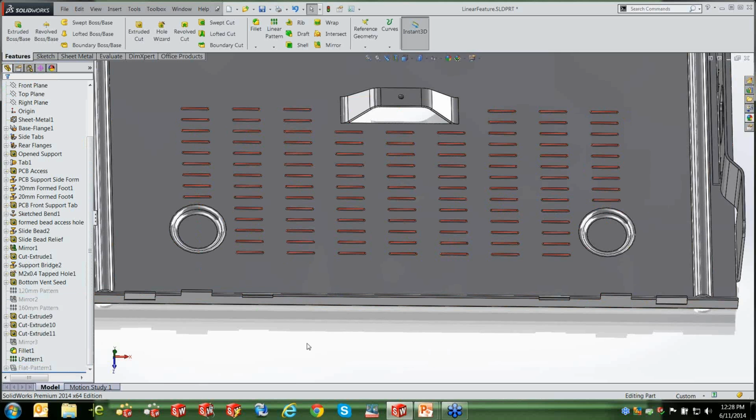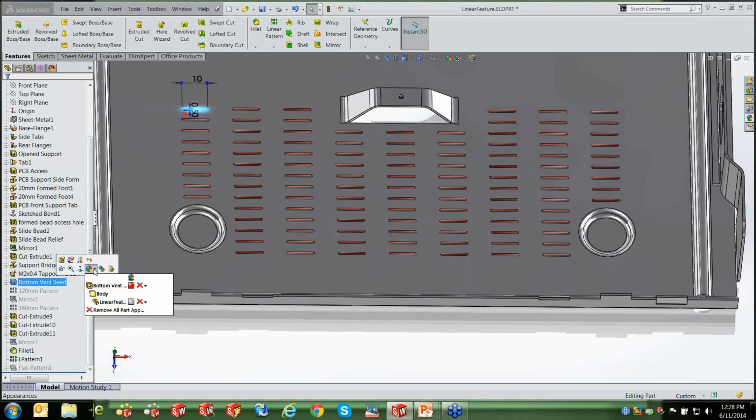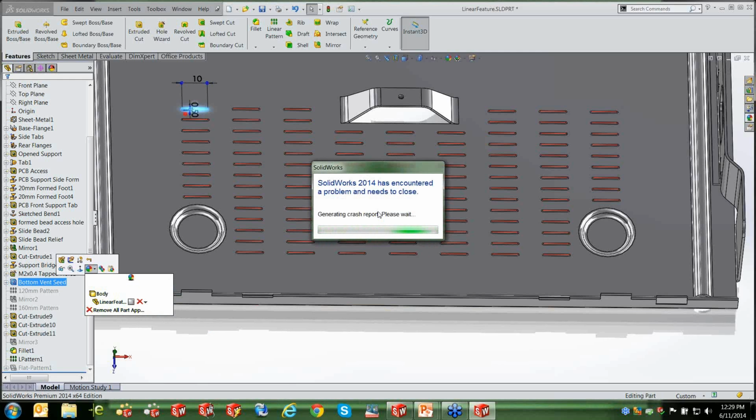Very simple. The gotcha on that one is when you go to change the color, you've got to make sure you change it and apply it to the feature, because it's moving the feature colors along with it. It will see if there's an individual face, but if you have a body or some other hierarchical color, it may not move it along for you. Okay.